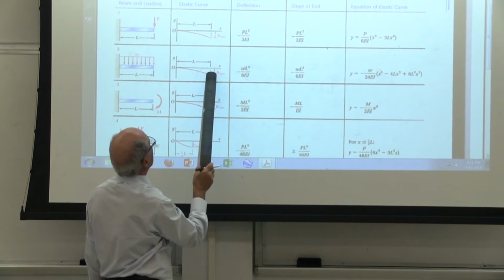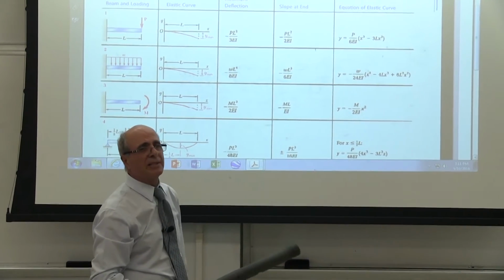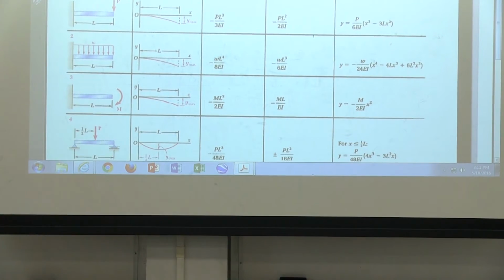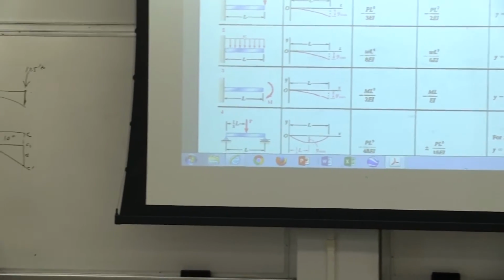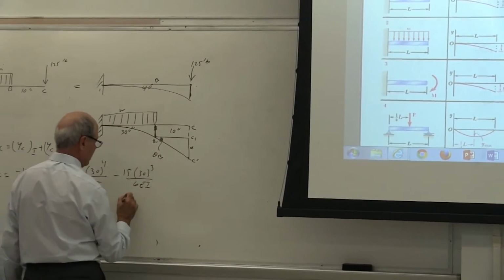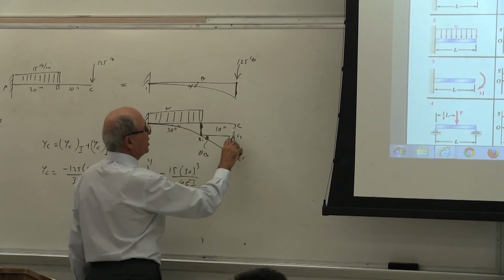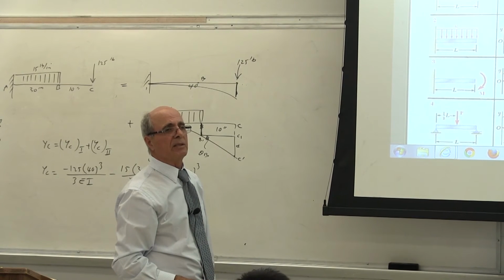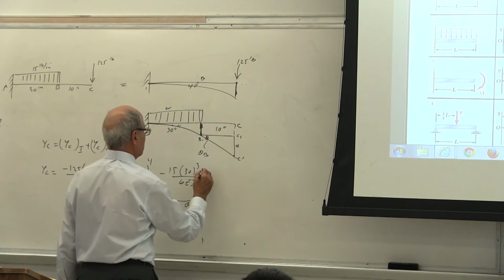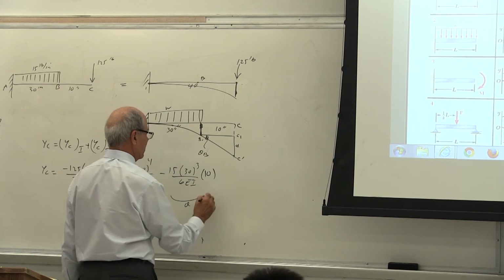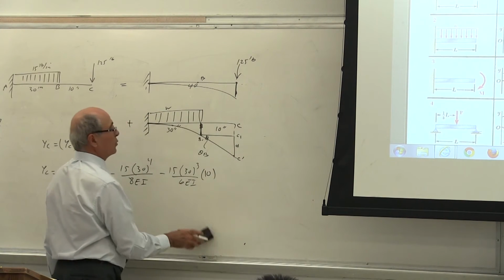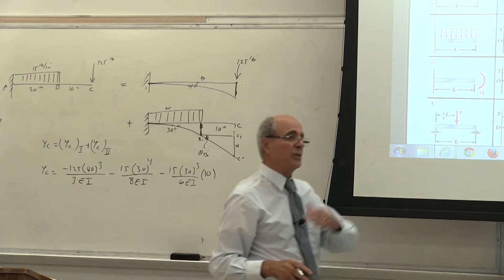The slope at that point is minus WL cubed divided by 6 EI. So you write the slope there, minus W times 30 to the power of 3 divided by 6 EI, which is the theta. You need to multiply it by 10. Is that correct or not? To get the distance. So multiplied by 10, the unit works, etc. And this is a. So that's what I put there. Theta and a. You have to use this technique anytime you go beyond the load.